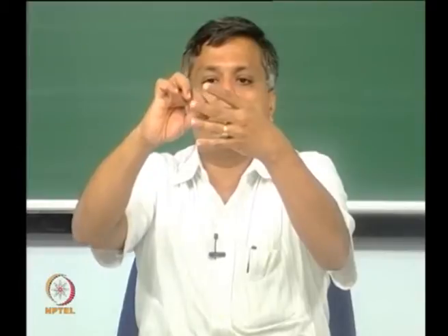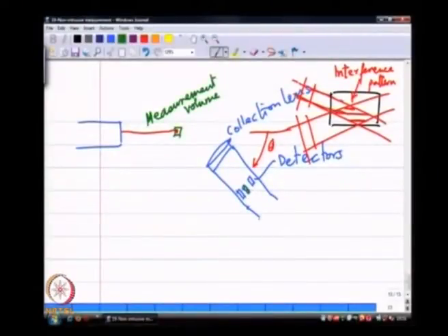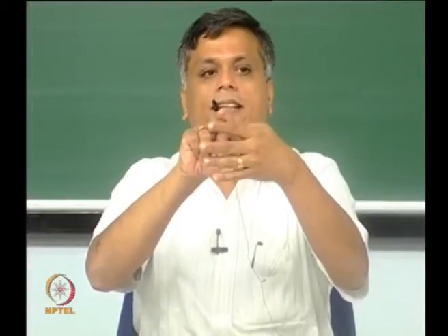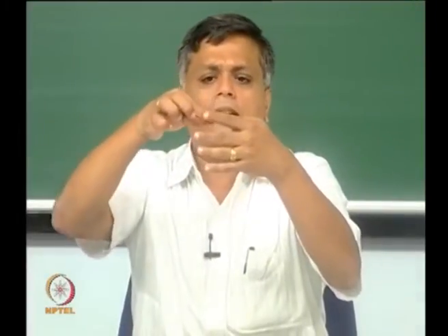As far as the velocity measurement is concerned, imagine a particle going through these fringes, and I have one detector here sensing the light scattered from the motion of this one particle. If I plot the intensity measured by one of these detectors, I will call them 1, 2, 3, the intensity I2 measured by detector 2 as a function of time, I will see the drop scatter light, or the detector sees the drop, when it is in the bright part. When it is in the dark spot, you do not see the drop. Then again you see it, like a little speck that appears and disappears. That is a simple mental image that you can carry with you.